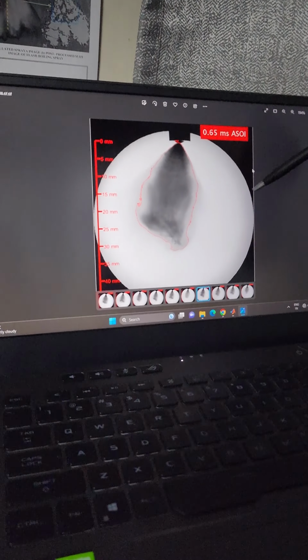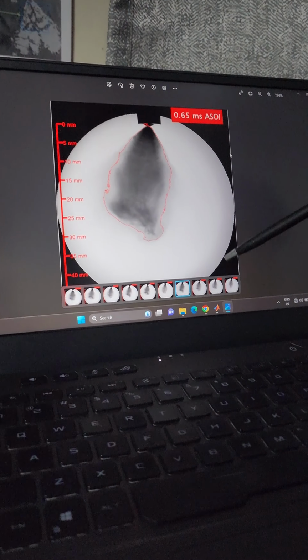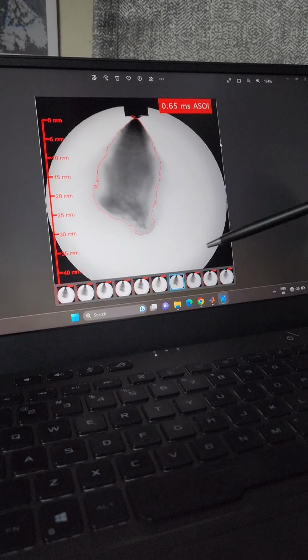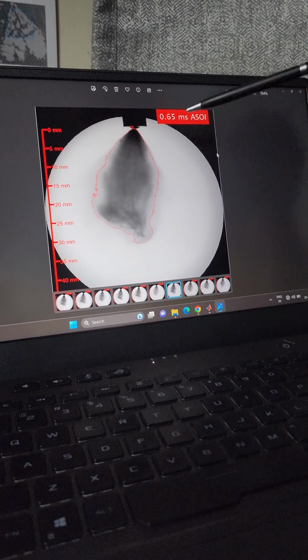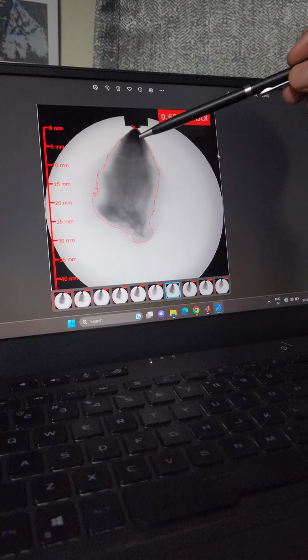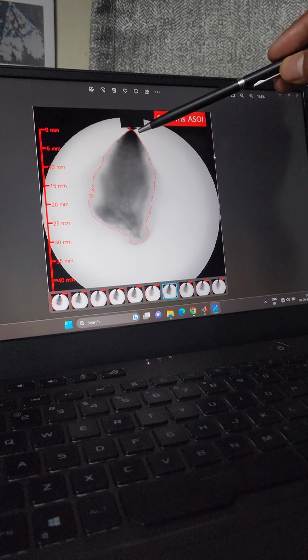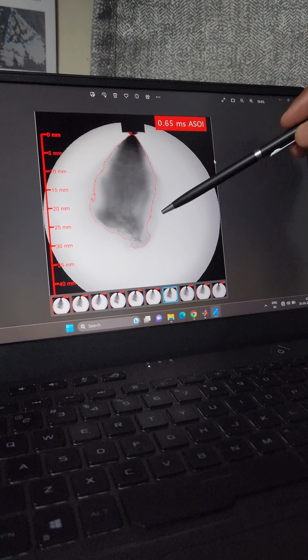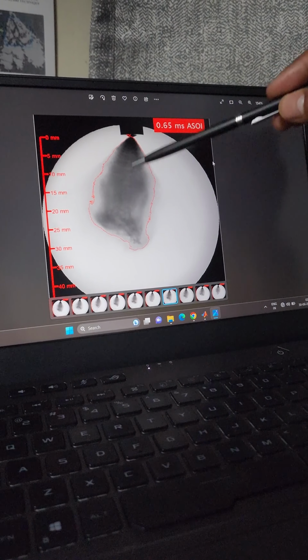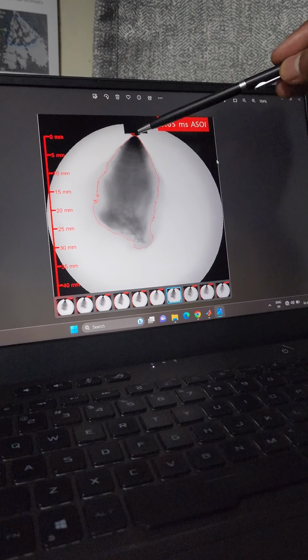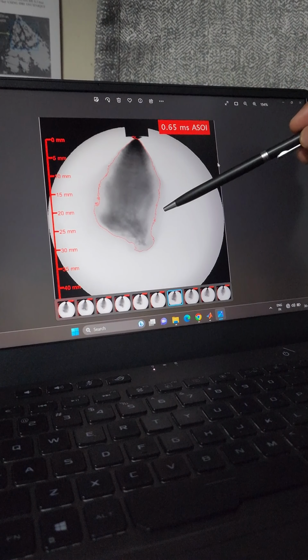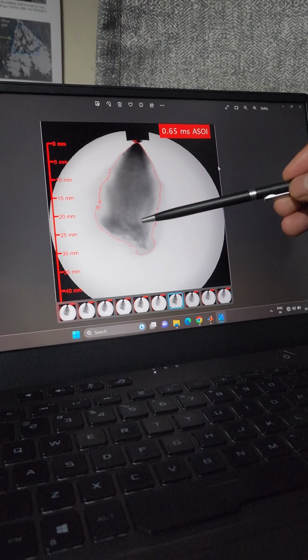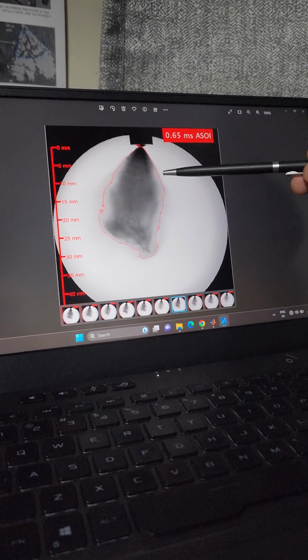The spray images obtained from the laser based diagnostic technique are then further post-processed using the MATLAB script. In the spray images, we have to extract these details, like the boundary of the spray, how far it is being developed, the extent, the width and the cone angle of the spray, and at what time this spray has been captured.